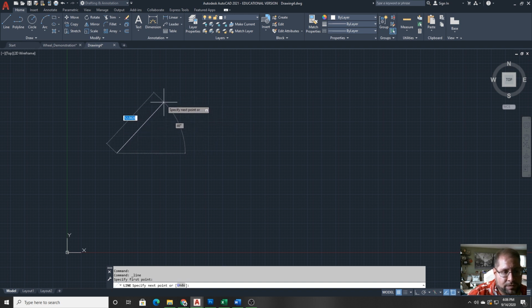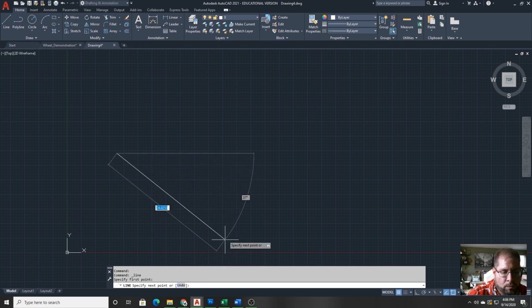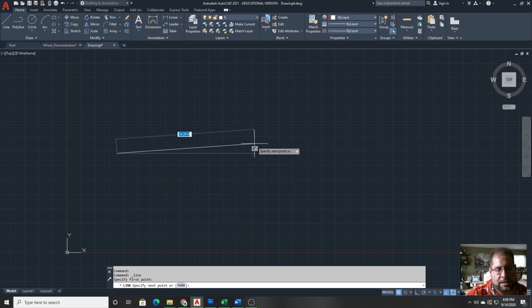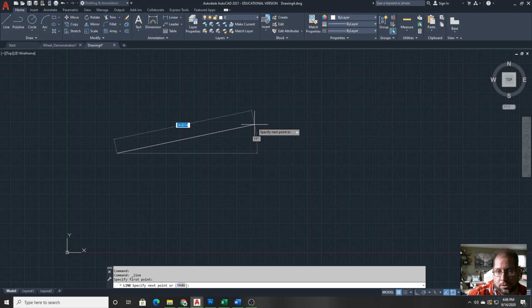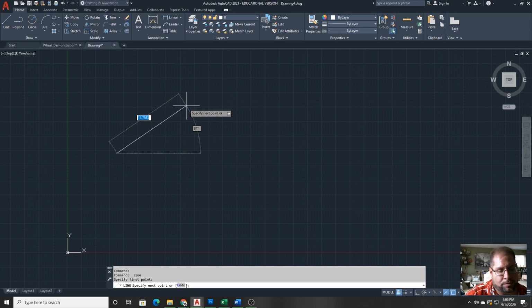As you can see, after I drop my first point down, I have an option that popped up on the bottom of the screen to undo that point. We call those options context-sensitive options, and in addition to them being context-sensitive, they also have keyboard shortcuts associated with them that come up highlighted in blue. So if I press the U key right now, it would undo that first point. Watch what happens when I click and drop the second point to complete this line.